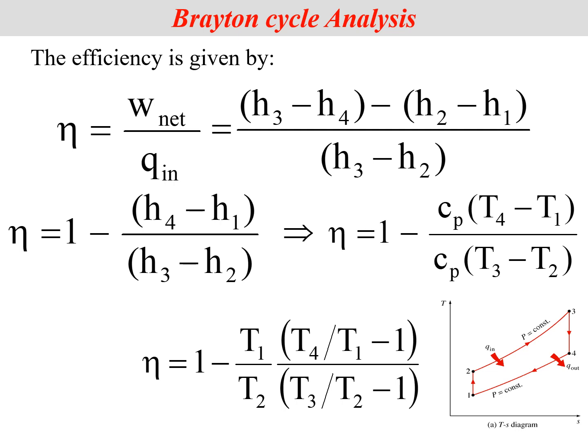When you have done all of these, then you have W net which comes out to be W out minus W in, divided by Q in. So this equation is also represented by 1 minus Q out by Q in. Okay? So Q out by Q in.